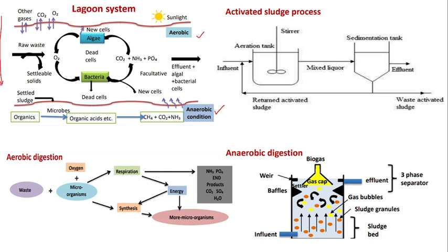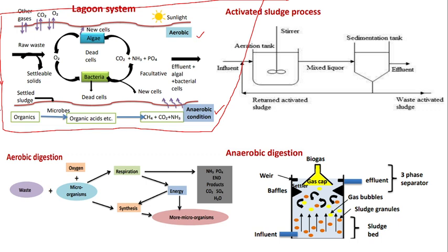Say, for example, this is a pond. So this pond is completely maintained for a particular period of time. So what happens? This is the sludge. Sludge is formed at the bottom. Wherever the sludge is, the oxygen is very minimal. So the organic matter will be converted by the anaerobic microorganisms into organic acids, and finally it is released as methane and carbon dioxide gas. And then at the top, it is having interaction with the gases. So oxygen is coming in contact with the waste matter.